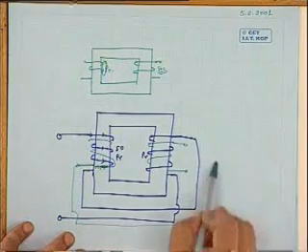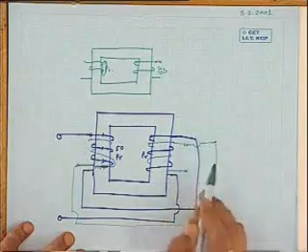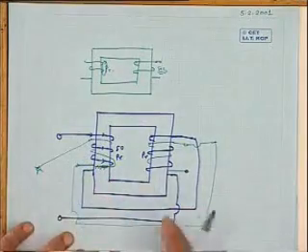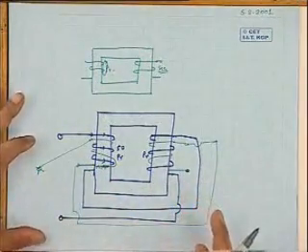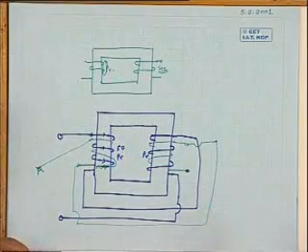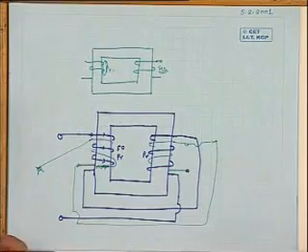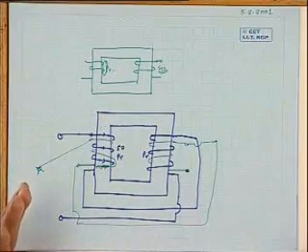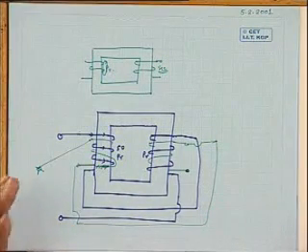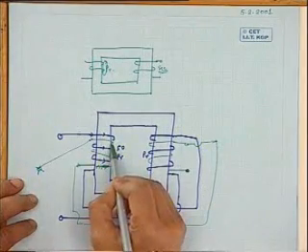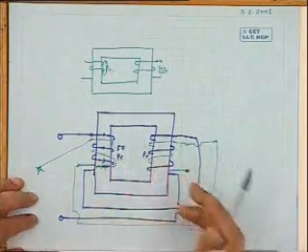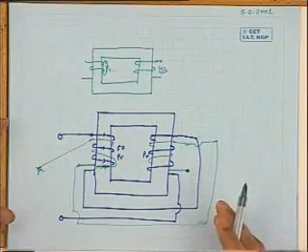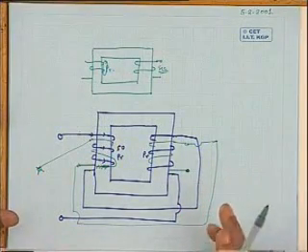In the same way this one will be, I don't want to complicate this diagram, it looks complicated but not at all. So your two secondary terminals will be this one. This green one is the secondary coil, this one is the primary coil. Now obviously leakage flux will reduce, because on the same core you have both primary and secondary linked. There will be leakage flux linking only the secondary, but because of their closer proximity, that will certainly be reduced.